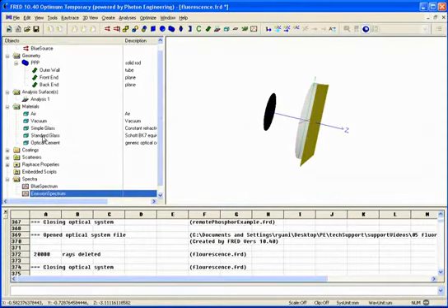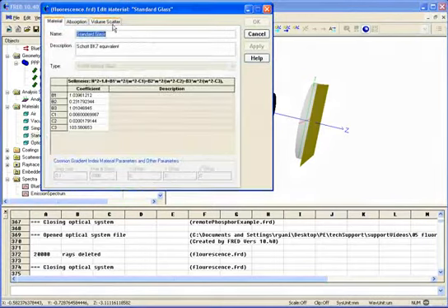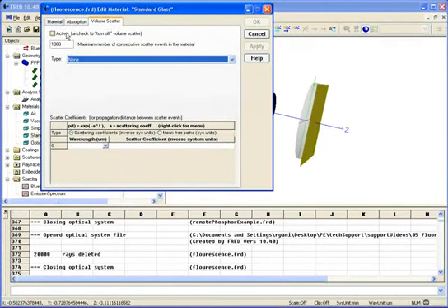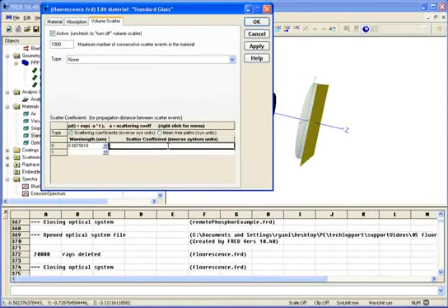Go back into our standard glass here. Click on the volume scatter. We're going to turn volume scatter on. I have to specify a scatter coefficient here. 1 will do. It's going to use that for all wavelengths if there's only one defined. Let's give it 0.1 mean free path in system units. So that'll ensure that probably scattering 1 time as we pass through this volume here.